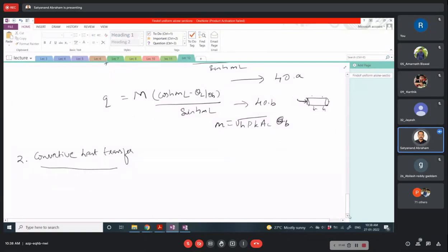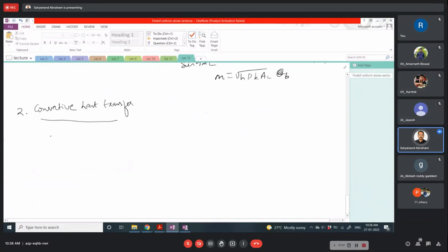So now we are going to see the next boundary condition, which is the convective heat transfer. We can see at x is equal to L, what we are saying is minus k d theta by dx is equal to h tip into theta at x is equal to L, because we already have considered this heat transfer coefficient h over here, which comes into this term m also. So h tip is different, which is h at the tip.